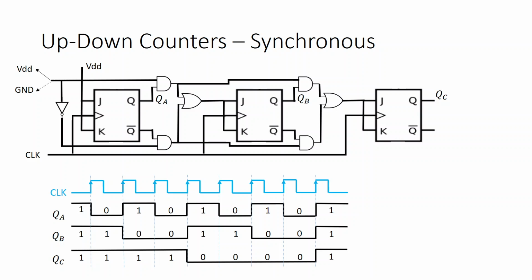So what is happening here? When we have connected this particular bus with VDD, then this is connected with 1 here, and this is connected to 0. So all the outputs of these lower AND gates will become 0.